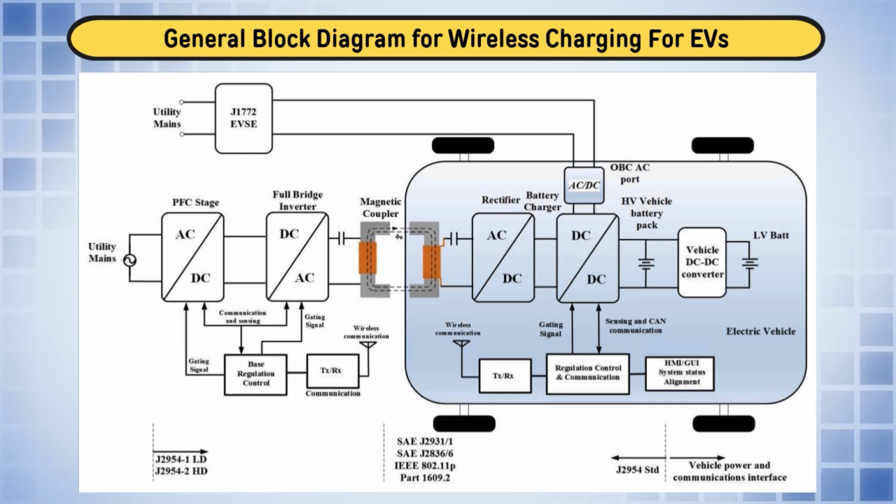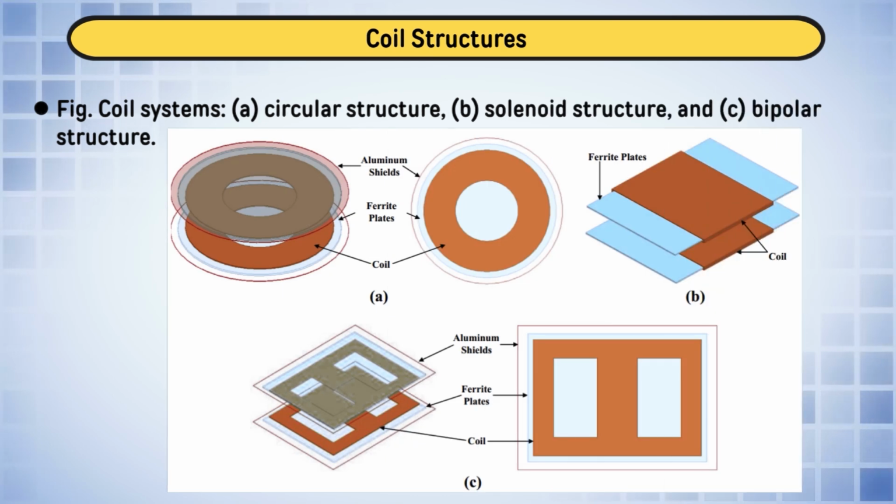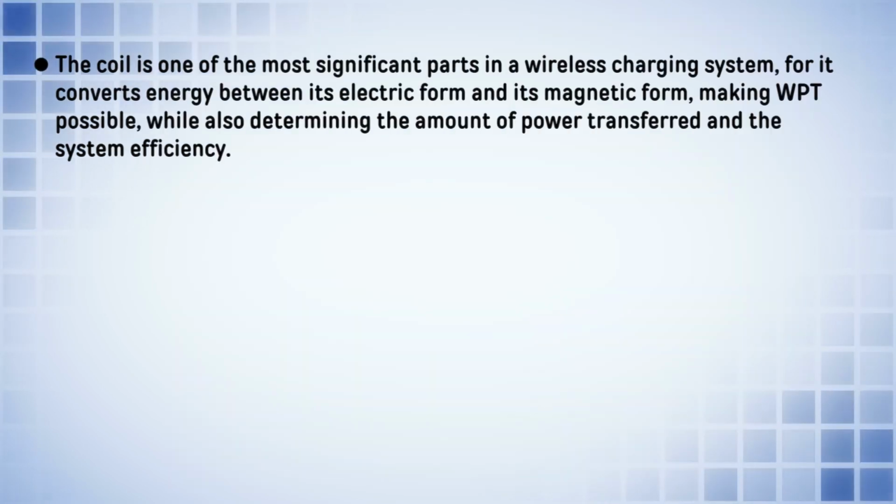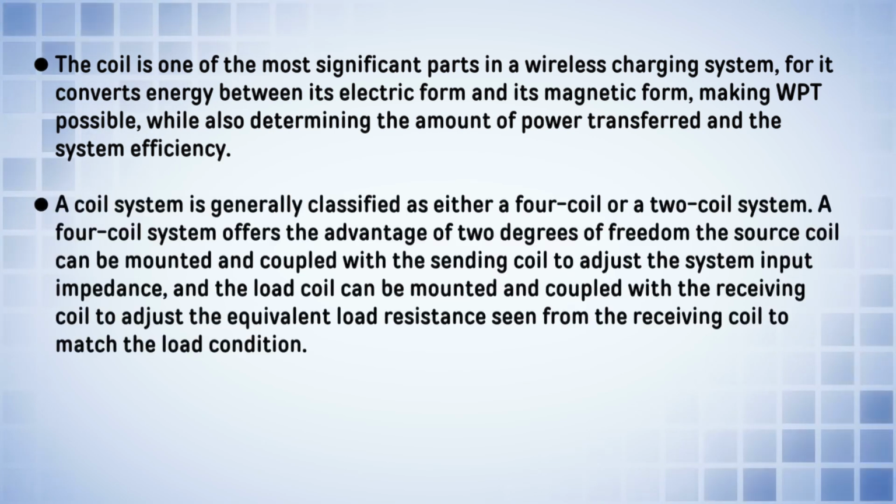In isolated converters, we have multiple switch based converters and single switch based converters like boost, forward, buck, flyback, where one inductor and one switch and then a transformer are utilized. However, one diode is also used in that case. However, we have multiple switch based converters, and these are named push-pull, full bridge, half bridge converters.